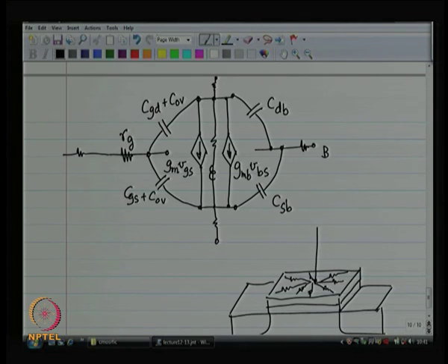So, it is like there exists an inductor over there, which tries to continue with the current that was flowing before and slowly allows a build up of current. So, it is not really like this, it is a distributed inductor resistor network. The whole thing is distributed, right.